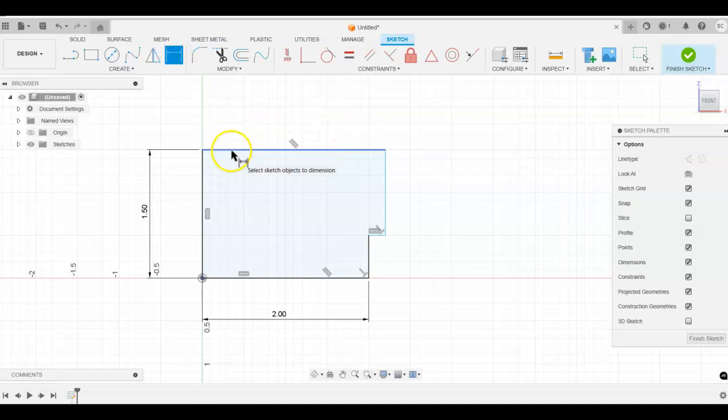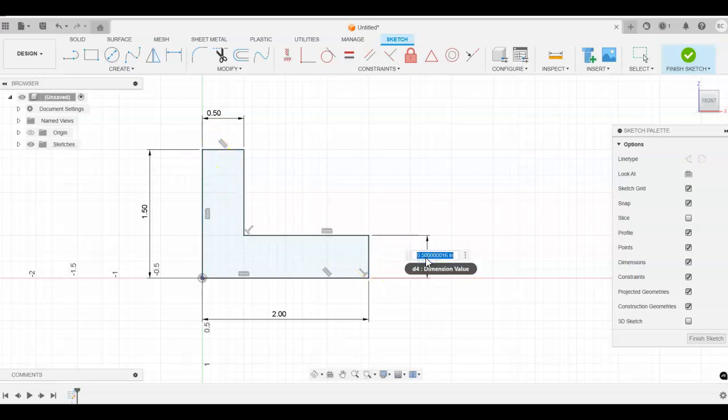So each of these legs is going to be a 1/2 inch. So I'm going to change this now. Notice when that got moved around, it became a line with a length of 2.2. Now I'm actually applying a dimensional constraint. I'm saying that this line can only be a 1/2 inch or 0.5 long, and that pulls that in and is now dimensionally constraining the length of that line. Let's do the same thing here. And this one is also going to be 0.5. So now I've got everything dimensionally constrained here on this part.